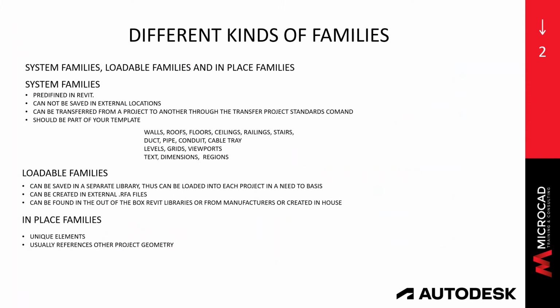I have an issue with in-place families, and in general, I advise not to use them because they are only available in the project where they're created. As you're going to see throughout the webinar today, creating families is involved, and there is a lot of things that you have to think about. So for me, these in-place families, stay away from them.